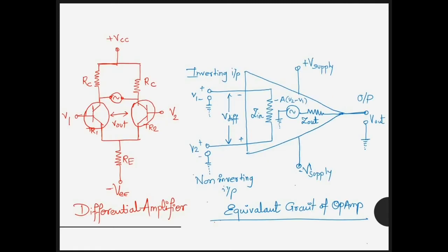Here, the circuit for the differential amplifier is shown in a generalized form with the two inputs marked V1 and V2. The two identical transistors TR1 and TR2 are both biased at the same operating point with their emitters connected together and returned to the common rail -VEE by way of the resistor RE. The circuit operates from a dual supply, plus VCC and minus VEE, which ensures a constant supply. The voltage that appears at the output Vout of the amplifier is the difference between the two input signals, as the two base inputs are in antiphase with each other.